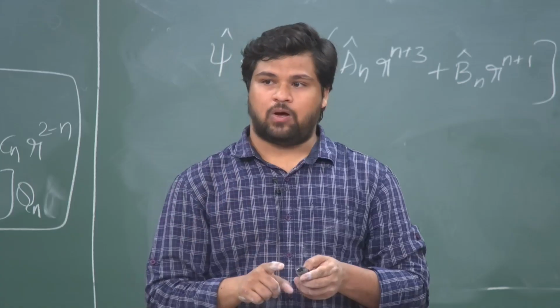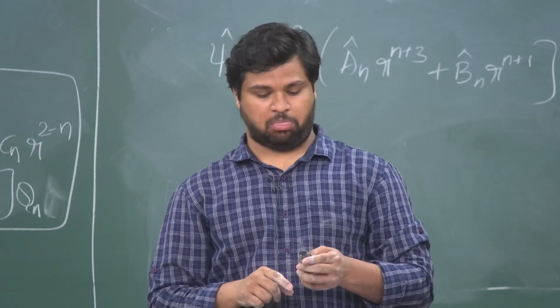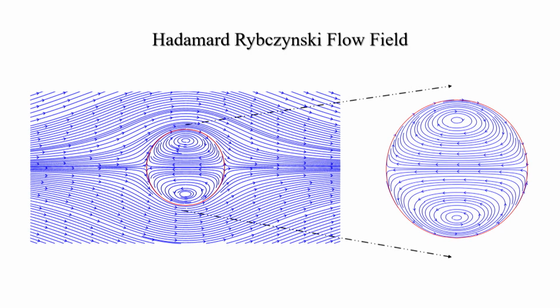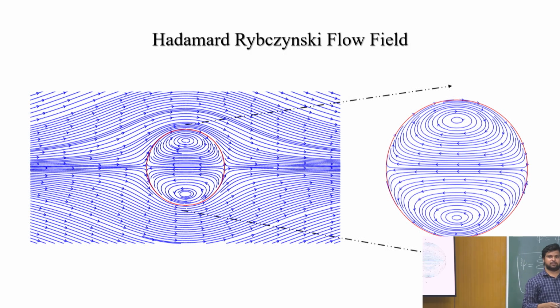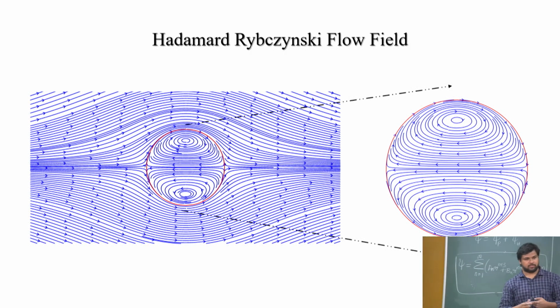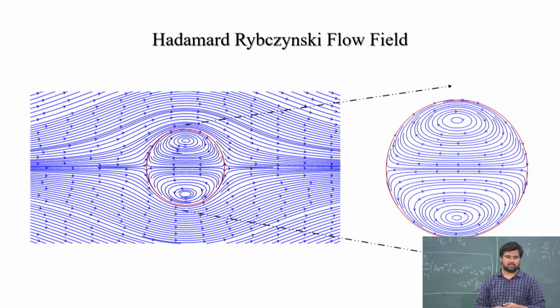If you plot your Vr and V theta, these are the internal circulations you will get. You can see here how the fluid is moving inside. This will enhance your micro and macro mixing, which will help in homogeneous distribution of reactions and all.